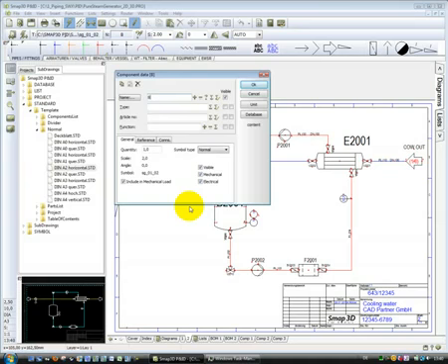And then the next intelligent function of the system comes up. This mask we can see is called component data. In this component data mask, the software requests the user for the unique number of this new symbol. The unique number has a specific name, and this tag number is requested here. A tag number specifies a unique number of a component in a P&ID diagram.